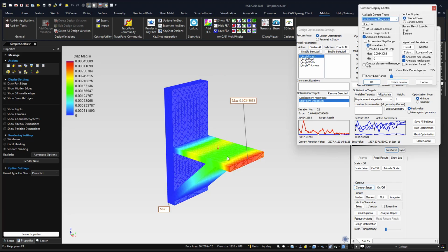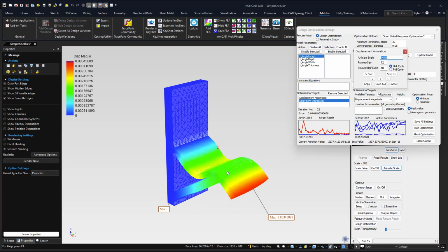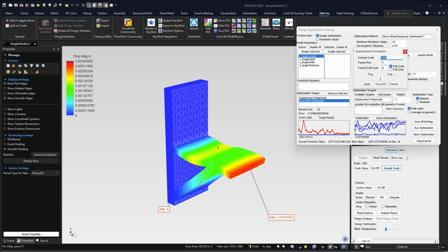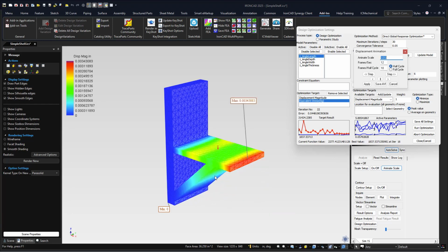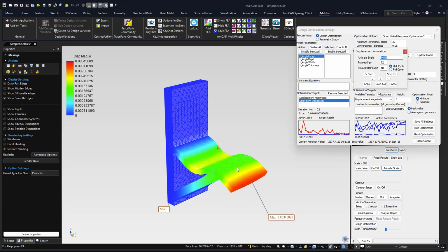And we can see it's still in the same displacement, but it's a lot less than what it was in the beginning. So we can change those variables to see those results, and again, you can animate it and see how different the model works based on where this brace has now been adjusted and modified based on its thickness, the width, and the location of that start along the X direction and the Z direction there.